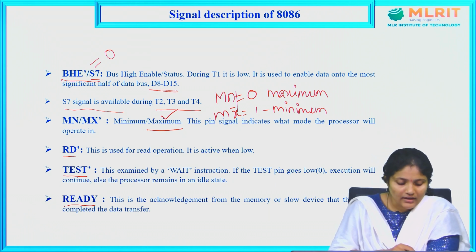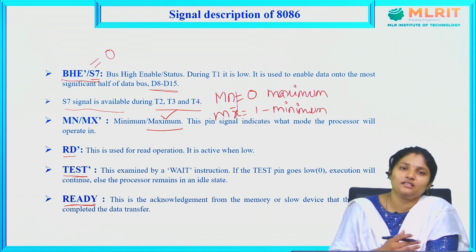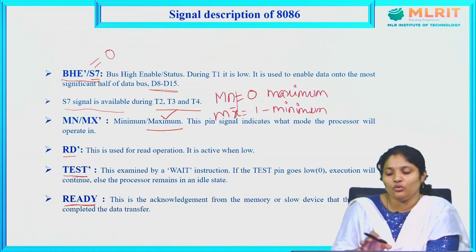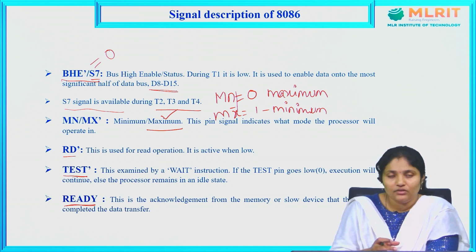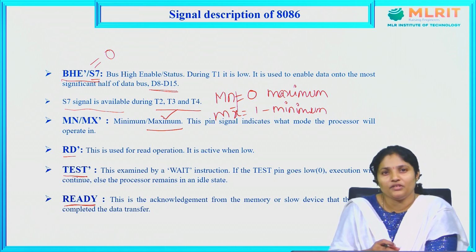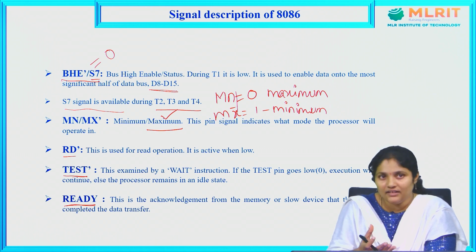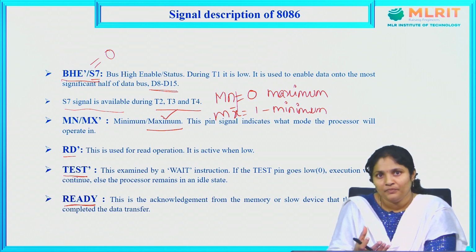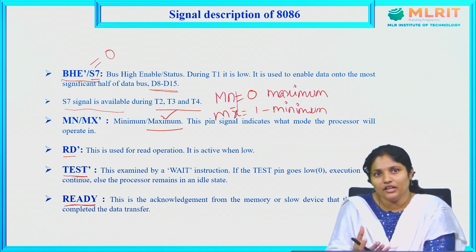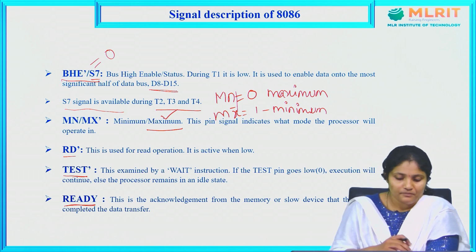Here, ready is nothing but the acknowledgement from the slow devices or the other peripheral devices interfaced to the microprocessor, that they have completed the data transfer, have completed their job, and are ready to transfer the data.